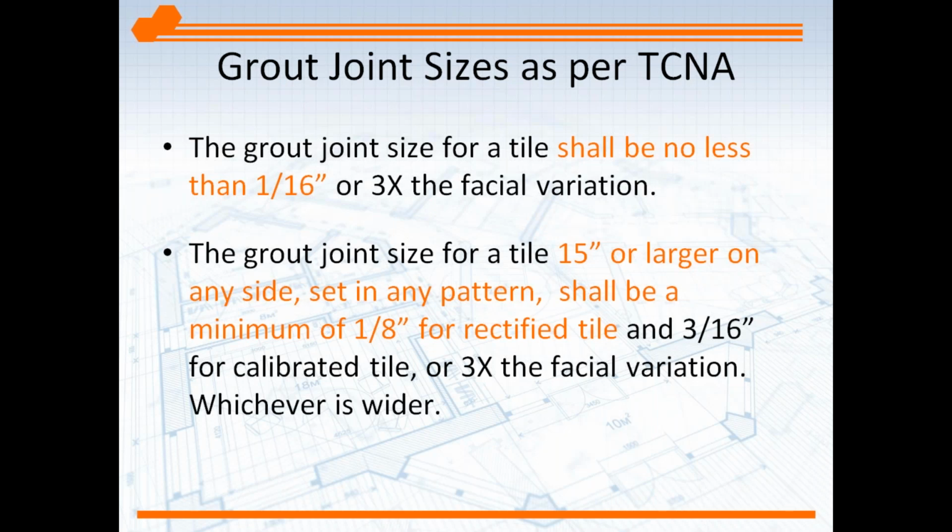For 15 inches or larger tile, they recommend a minimum of 1/8. Okay, and if it's not a rectified tile, then 3/16 on that tile. Rectified means machined, so the tiles are all about the same size, width, length. Calibrated is more of a measured tile rather than machined. They're not as exact, so they recommend a larger joint, 3/16, as opposed to the 1/8.